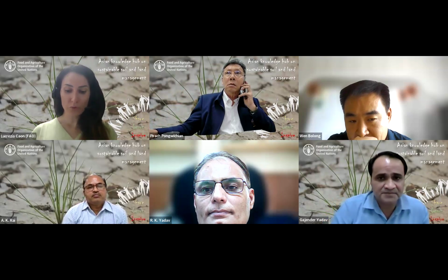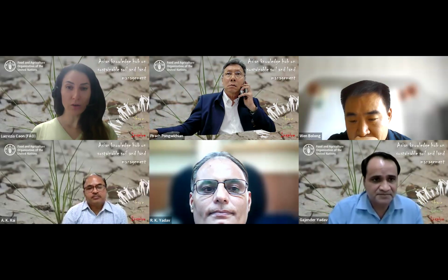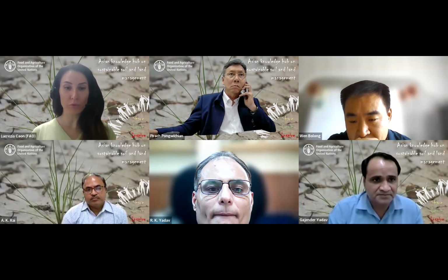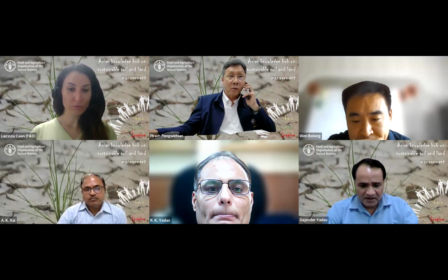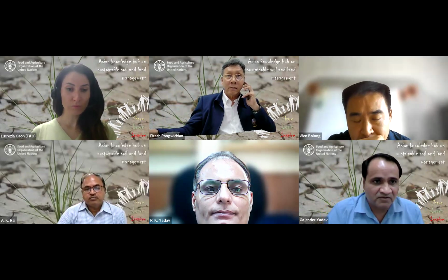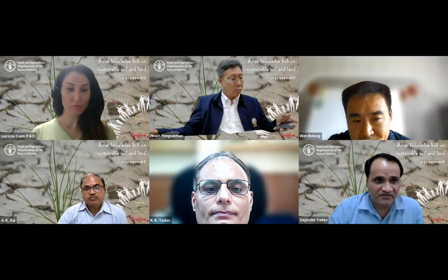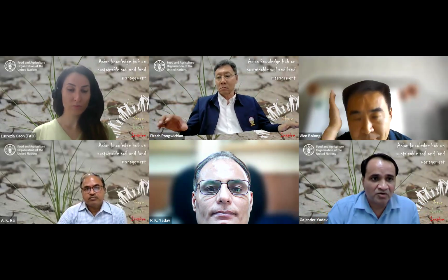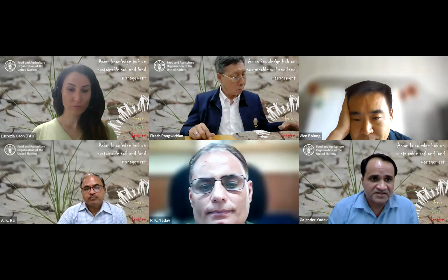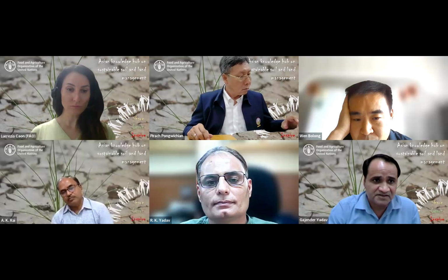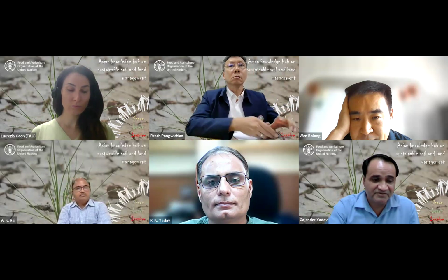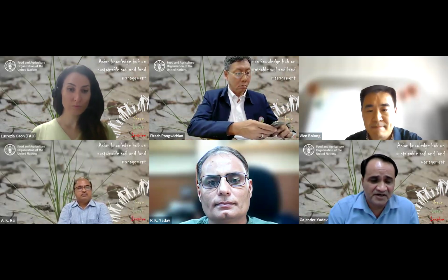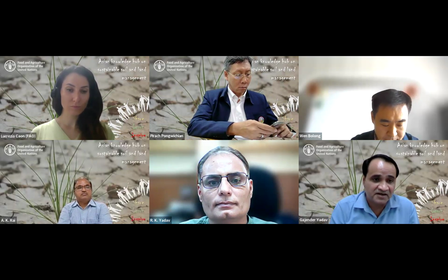Thank you. And then I was curious, is there any condition under which the subsoiler doesn't seem to perform very well? Yeah, it is not able to control when the water table is on the surface. It is generally effective when seasonal waterlogging is there, and the condition is that a slight depth is needed to construct the drain. Unlike drainage, it does not function when the water table is practically